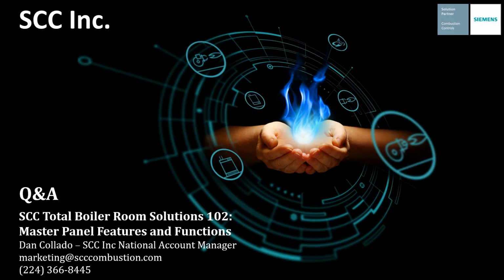In the case of a hot water boiler where the master panel is controlling the primary pumps or the isolation valve at the boiler, the associated relay contacts that are actually located in the master panel will fail closed so that the pump or isolation valve will run or remain open. This also ensures that the master panel doesn't affect the ability to operate hot water boilers locally. So good question for sure.